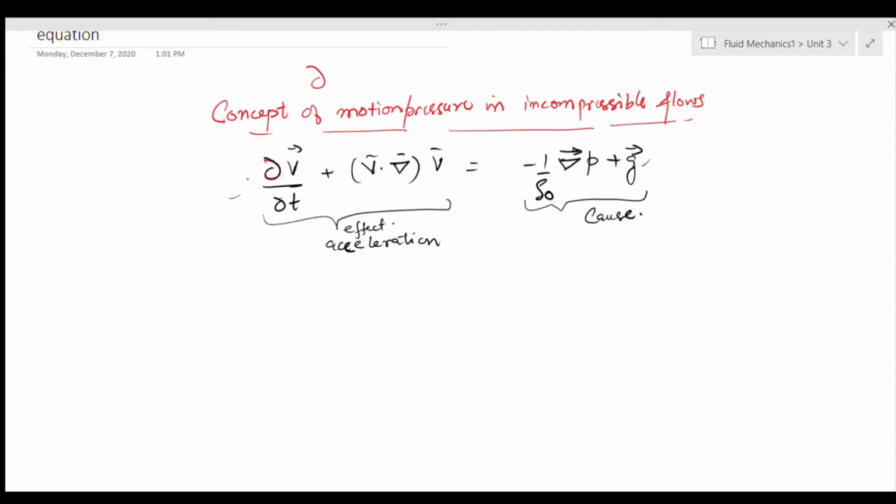To find that, let's say what would be the overall pressure if the velocity v is 0, that stagnation pressure, which if released would finally give us velocity v. So that bottled up pressure, how much would that be? And if we release that pressure, then how much velocity would we finally get?